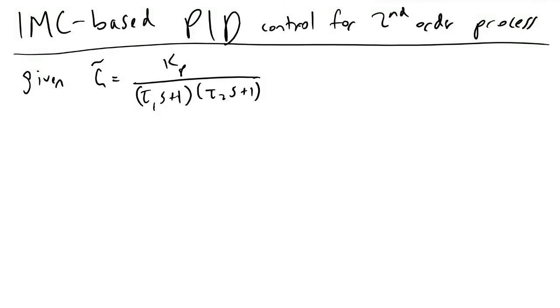Let's say we've been given some kind of physical process model that we have no control over, but we are tasked with designing a PID controller in order to regulate this process and respond to perturbations and disturbances in our inputs. When we're working with PID exclusively, we have 3 tuning parameters, one for each component of the PID controller, that we need to somehow determine.